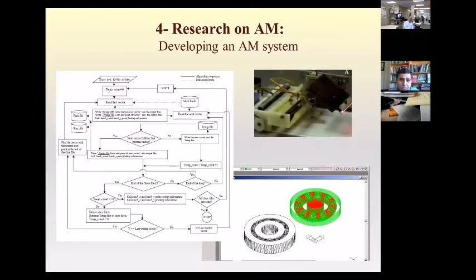As you can see, toolpath in this specific case was, if you want to make, for example, this bearing, you need to print in selected area in green and then hatching in the red area. You have to repeat that layer by layer. So it has a slicing, defining loops, defining also hatch. And you repeat that for all layers. Sometimes it takes several minutes to make that form.